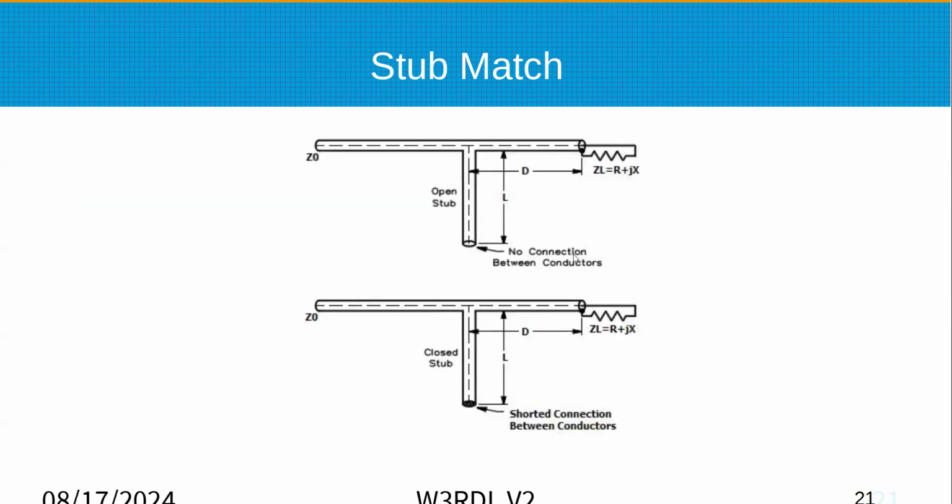So here's a couple examples where you have your normal transmission line coming in and it's connected to your antenna, where you have some load, which is the real part, the ohmic resistance and the radiation resistance, plus whatever the reactance is. So ideally, X would be 0 if it was at resonance.